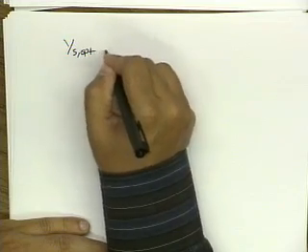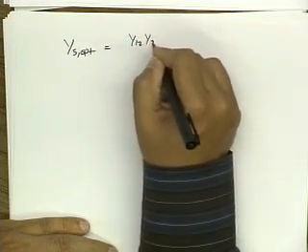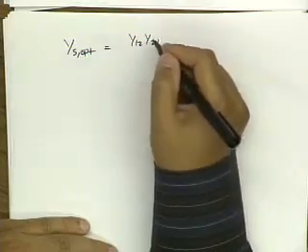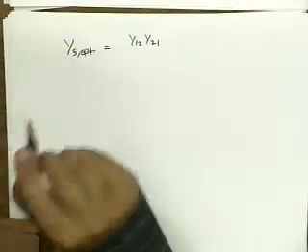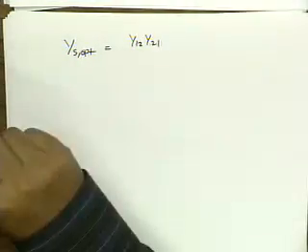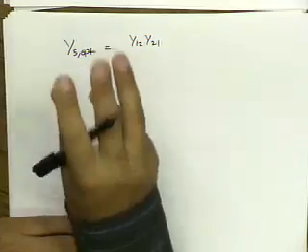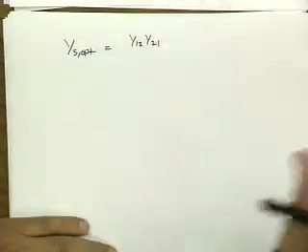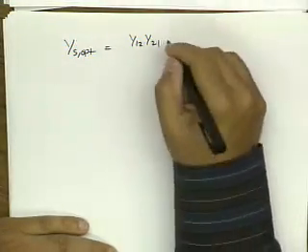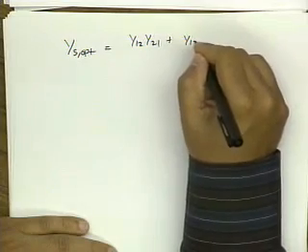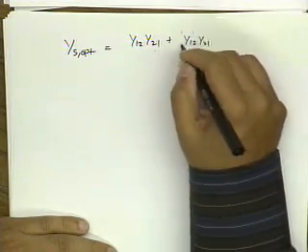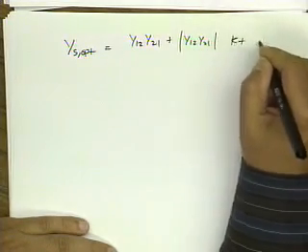For instance, the optimum source: you may say, how did I get the optimum source? I only calculated the optimum load. Well, you calculate the optimum source by simply saying that Ys should equal Yout star, or Ys star should equal Yout. So you go through the algebra and you derive these equations.